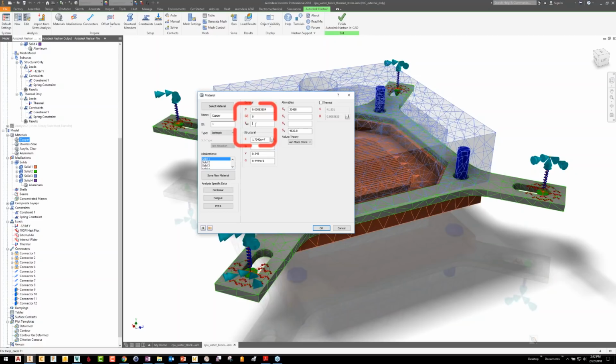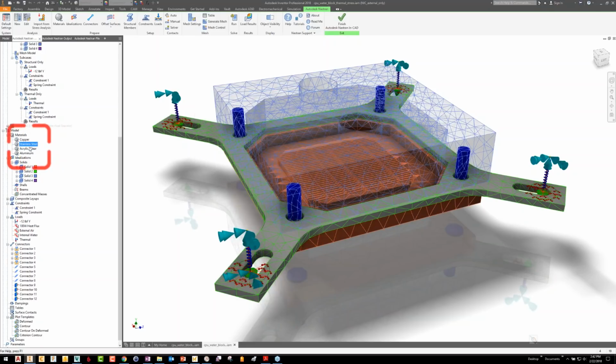So what you end up with is massive displacements, usually singularity errors. Thing just explodes. So if you forget to put this in, that's what's going to happen. You'll get either an error or these huge unrealistic displacements. Then you'll know, oh, I probably forgot to put something in that TREF field. So I'm going to go ahead and do that for all my materials now.